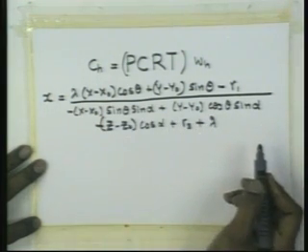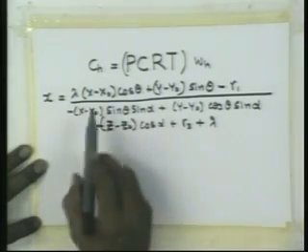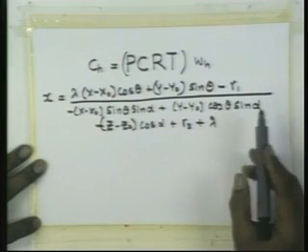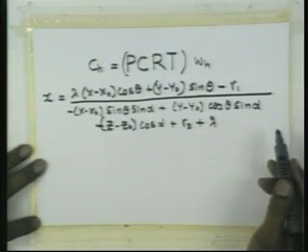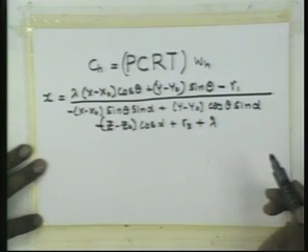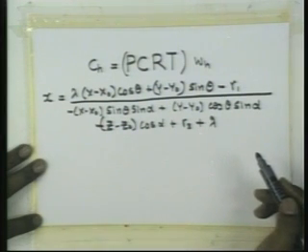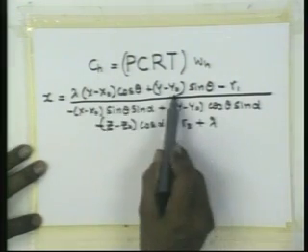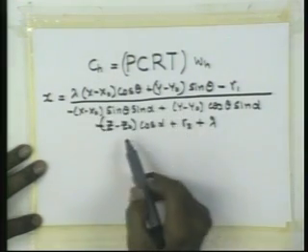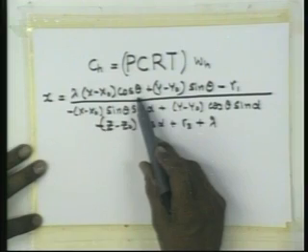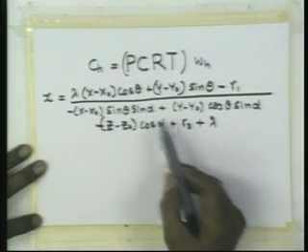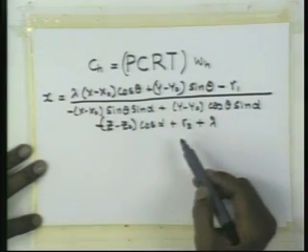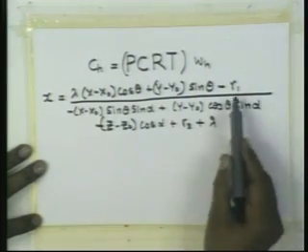Okay, this determines, so given any global coordinates x, y and z, right, and the parameters which define the location of the coordinate frame of the camera with respect to the global coordinates, which basically is determined by the offset of the gimbal center x naught, y naught, z naught, the pan angle theta, the tilt angle alpha, and the offset of the image plane center with respect to the gimbal center, which is r1, r2, r3.